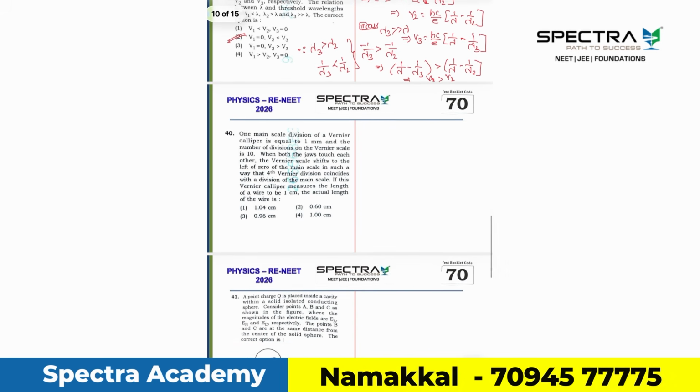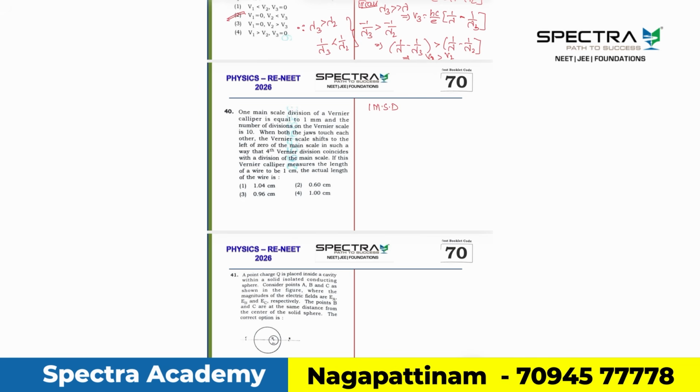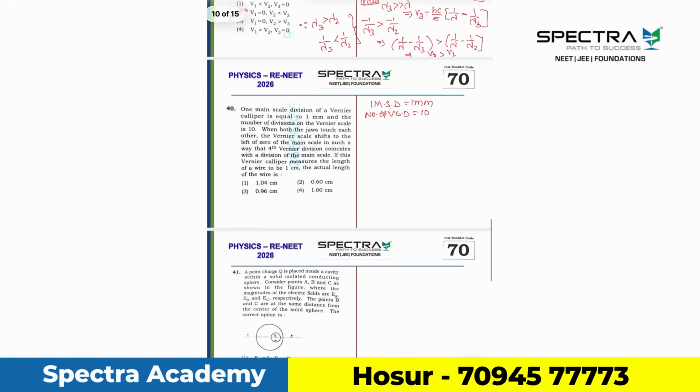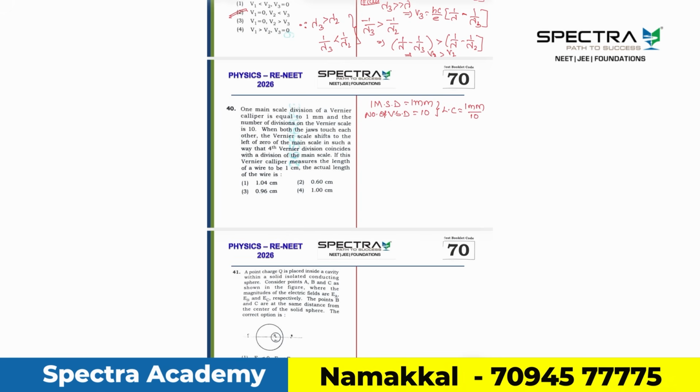Move on to question number 40. What they are saying to us: one main scale division value is equal to 1 millimeter, and the number of vernier scale divisions is given to be equal to 10. Clear? And therefore from this we can calculate the least count. Least count is equal to 1 mm divided by 10. Therefore, least count will become 0.1 millimeter, or we can write 0.01 centimeter.